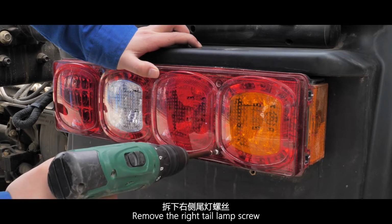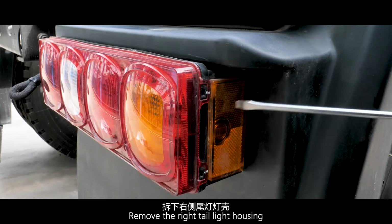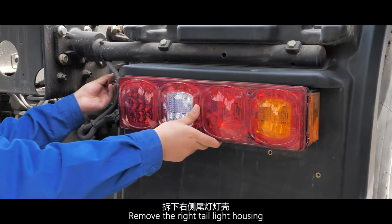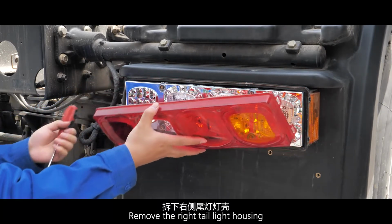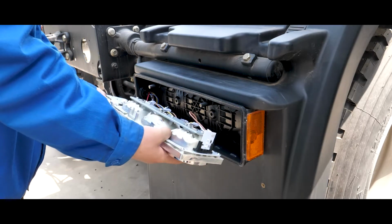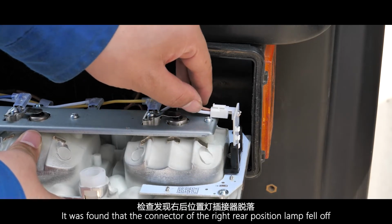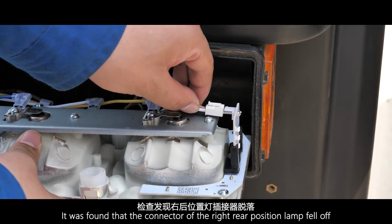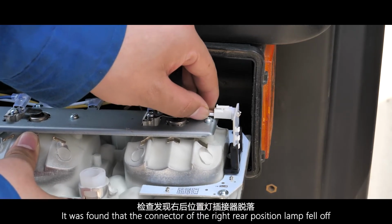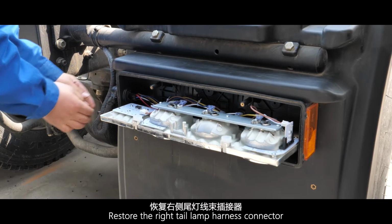Remove the right tail lamp screw. Remove the right tail light housing. Position of clearance lamp. It was found that the connector of the right rear position lamp fell off. Restore the right tail lamp harness connector.